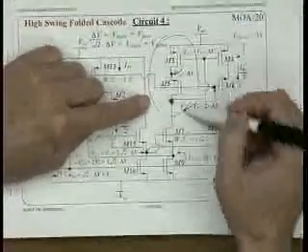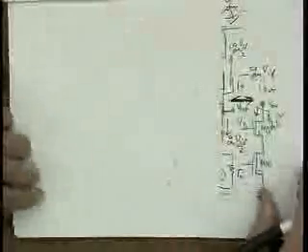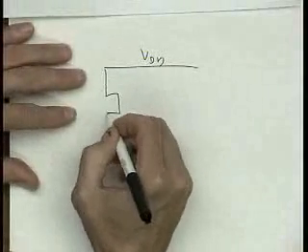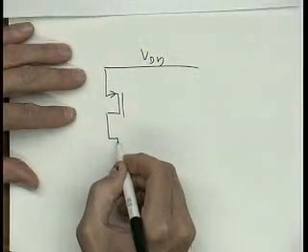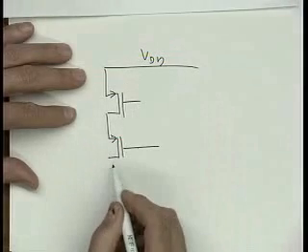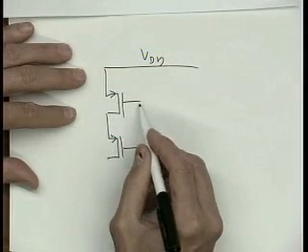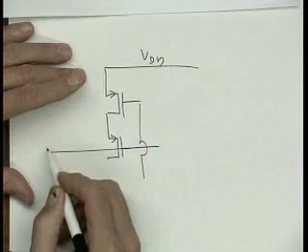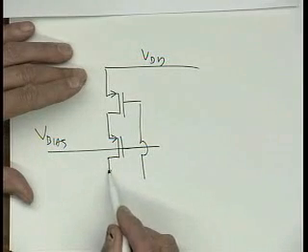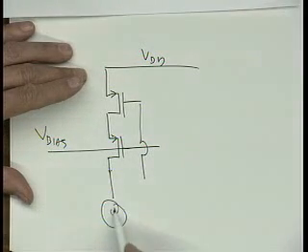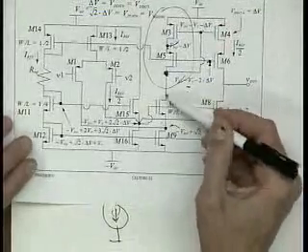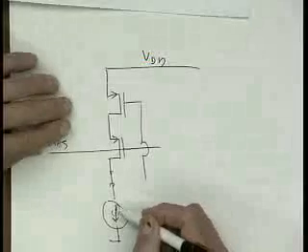Let's look at this right there. Let me just draw it out again. Here's VDD. Here's M3. Here's M5. Remember, this is going off to some bias voltage, okay? And this is going down effectively into a current source down below here. This is a current source here, and this is cascoded, so it's just a current source looking downwards. So effectively, we've got a current source down here.